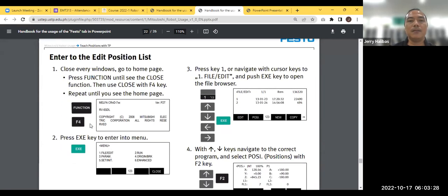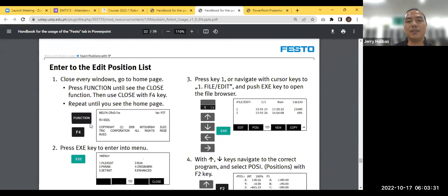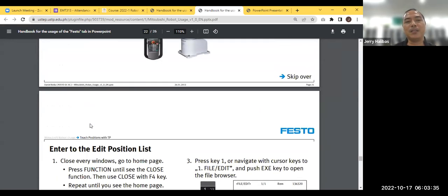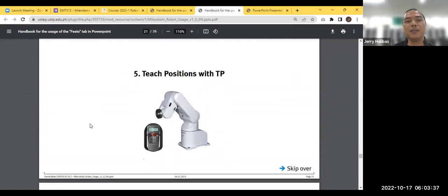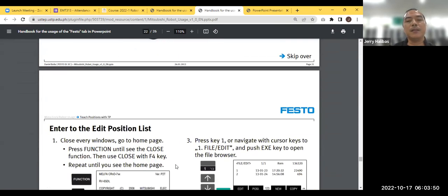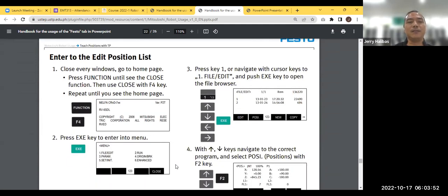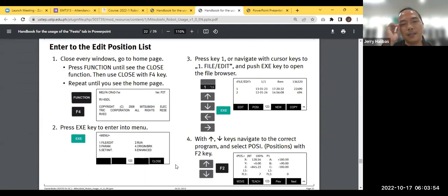Okay? So we won't cover that topic, because although it is still possible, we cannot teach the robot. Teaching a position requires the XYZ coordinates, so the joints must be complete without error. Since it gives an error, it is not allowed to teach a certain position, because by default it is Cartesian XYZ.